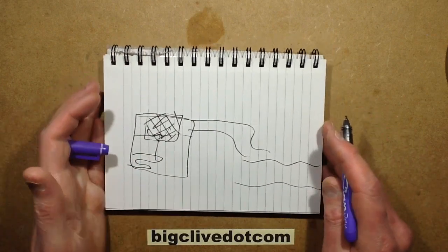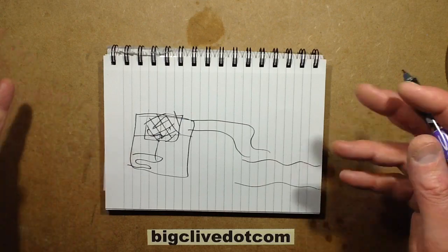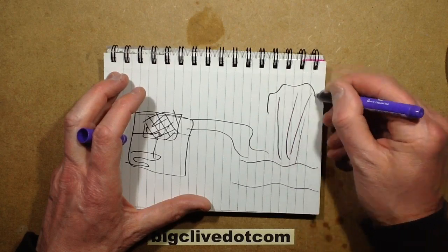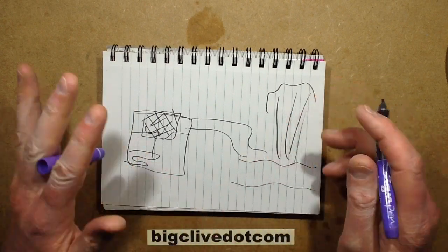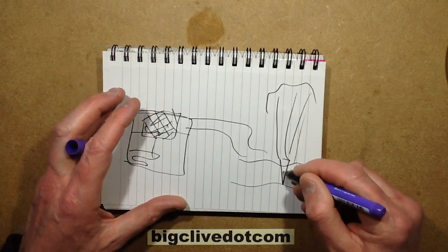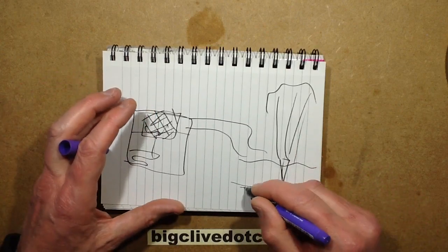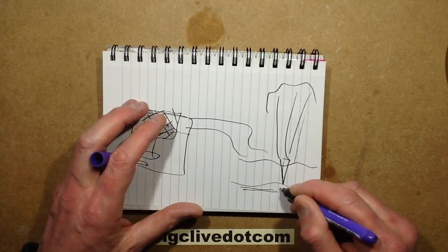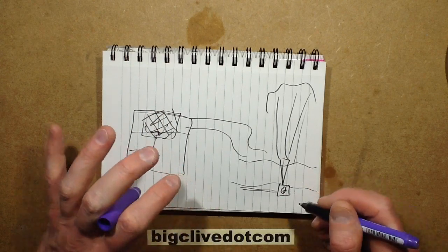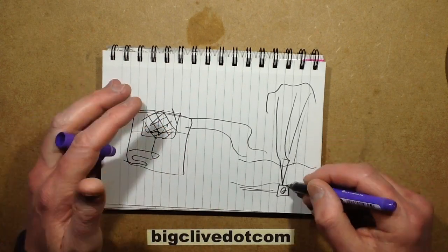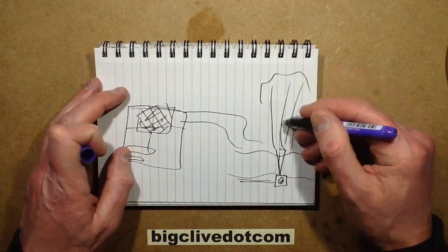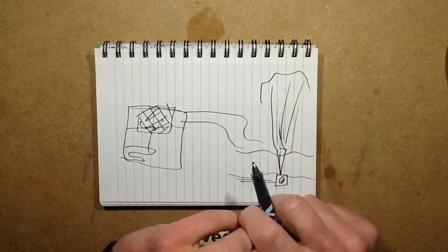In the case of the carbon dioxide jets, they're commonly used in rock bands, concerts, stages, to create that plume of fog that goes up and then disappears instantly. It really dissipates very quickly. All they're doing, they've got the conical jet, they've got a liquid feed of CO2 from a tank, and then they've got a cryogenic valve. It's important to use a cryogenic valve that's rated for those temperatures. It won't freeze up and stay open. And that's ultimately it. When they want the plume of fog, they energise the valve and it sprays the liquid CO2 out, and it instantly creates this fog in the air.